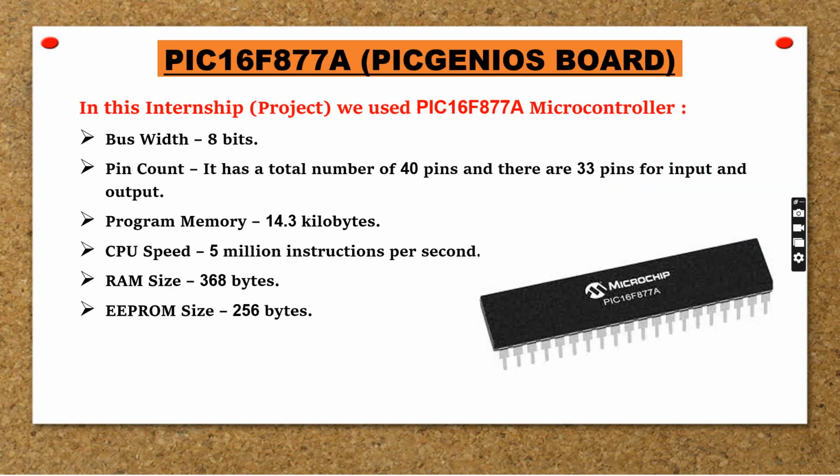So let's know about the PIC16F877A PICGenios board. This microcontroller is a widely used 8-bit microcontroller equipped with a powerful RISC CPU core operating at a maximum clock frequency of 20 MHz. Let's look into some of the functionalities of the PIC16F877A microcontroller. Its bus width is 8 bits. Pin count is 40 pins, and there are 33 pins for input and output.